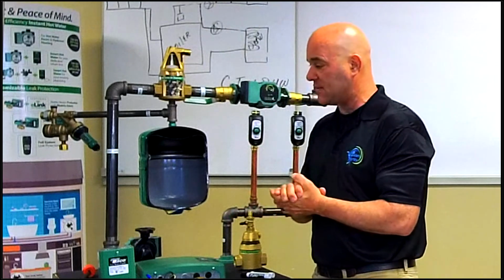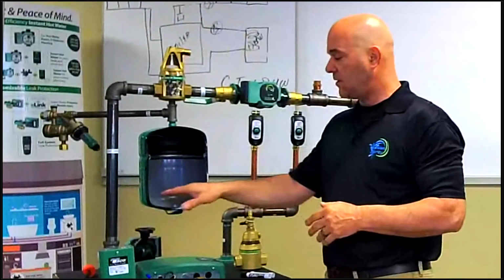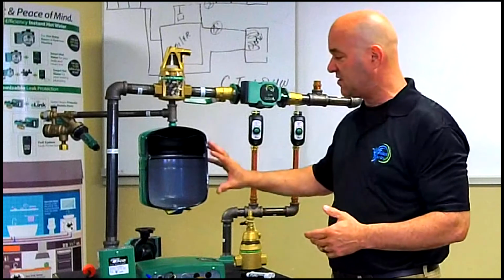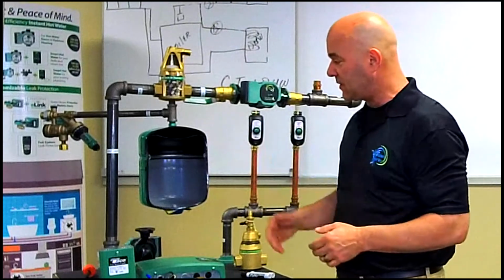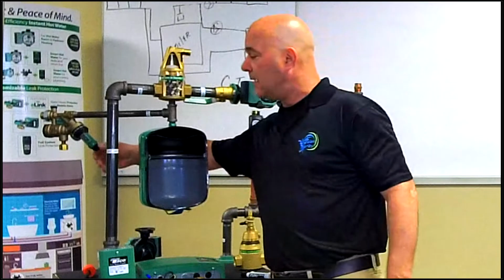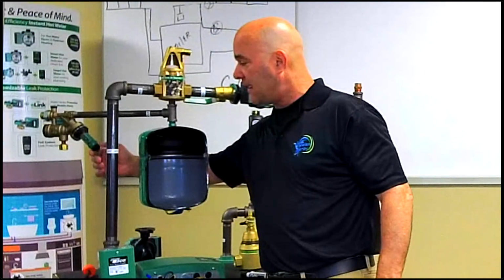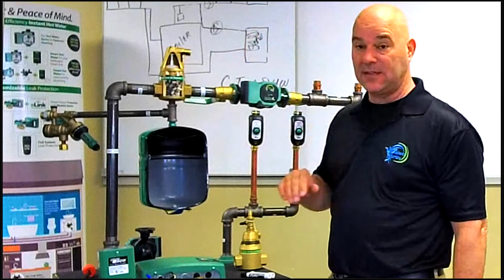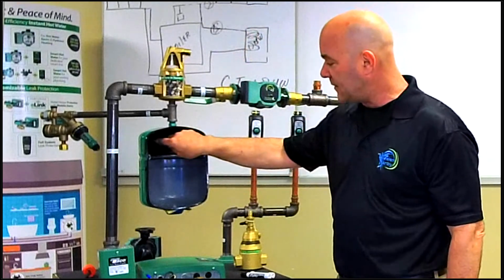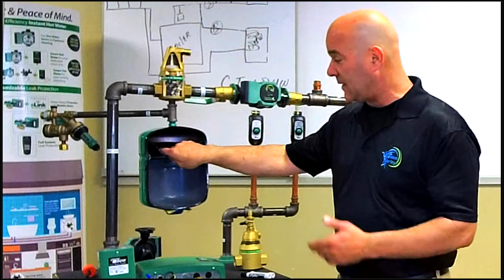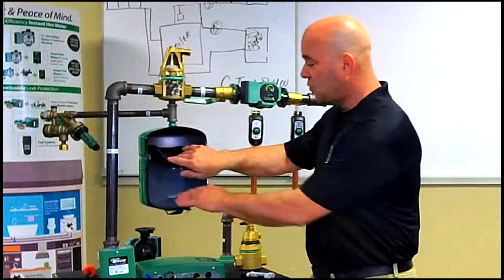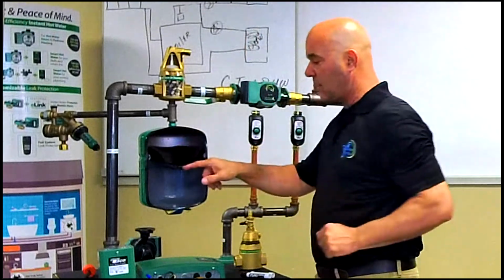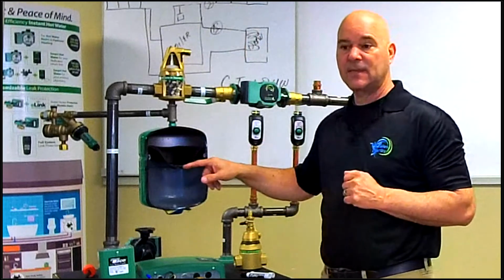I want to have an 18 PSI system, but I never adjusted my air side. What would happen? What would it look like? Because we normally don't get to see inside of an expansion tank. We have a cutaway here, so it makes it nice. I go to my feed valve and elevate this to 18 PSI, and I push the button and it's going to feed to 18 PSI. When it does that, because the 18 PSI is greater than the 12, I've now expanded and stretched my rubber diaphragm down like this.